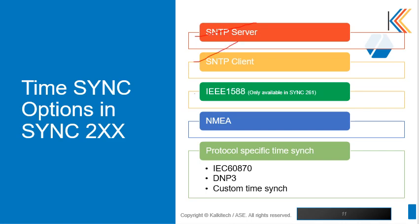The client is available. IEEE 1588, the precision time protocol, is available. NMEA is available for some custom requirements, and protocol specific synchronization like 60870 and DNP3 are available. You can set the priority, like IEEE 1588 will have first priority, and this protocol based synchronization will have second priority.